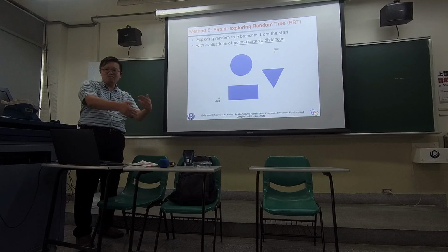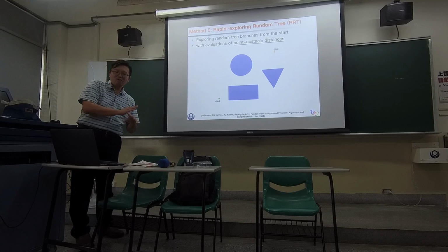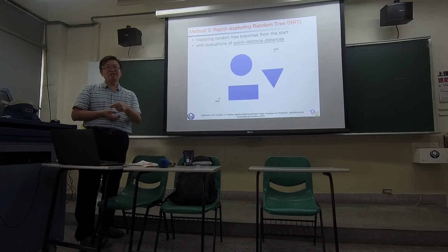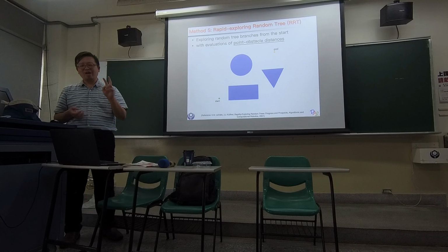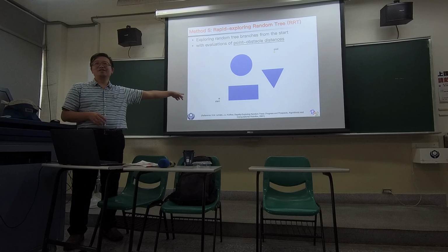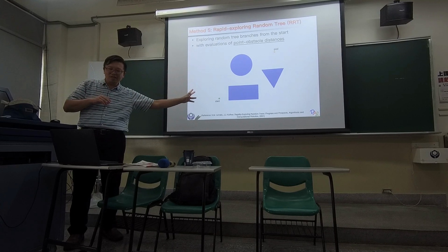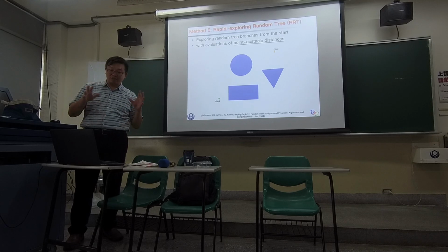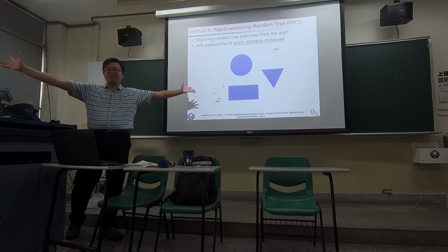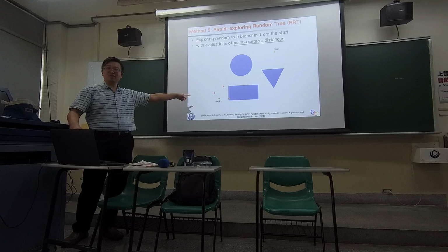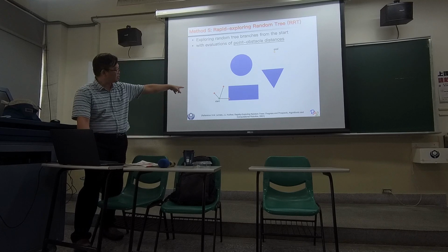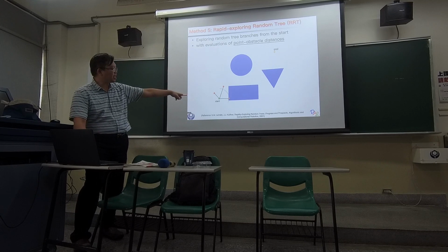Okay. So someone came up with a newer, more advanced approach, the so-called RRT, Rapidly Exploring Random Tree. The two most famous methods in path planning are A star and RRT. A star is easy; RRT, the procedure is more complex, but it's quite efficient. So they don't explore the entire space anymore. They start from the starting point, just explore your neighborhood. If there is a bad path, eliminate the bad one.